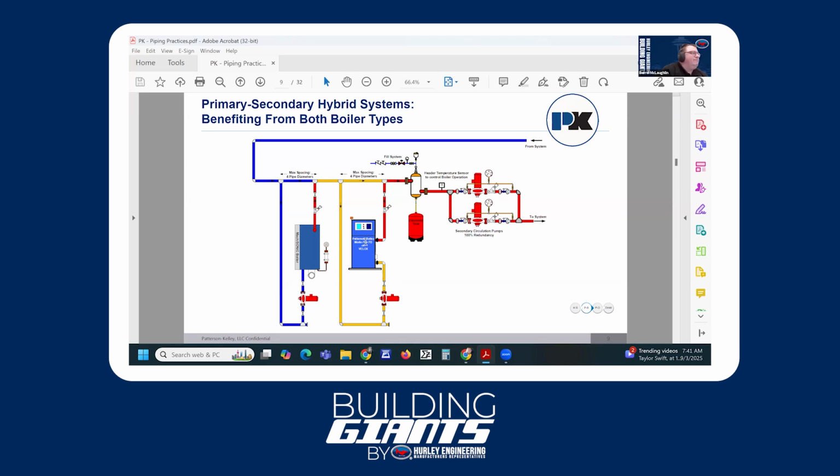Now that all relates to this: if we can get our return temps cool enough, then as they come back into the boiler, it cools our exhaust gases to the point where we drop below the dew point, and the moisture in there begins to condense. And once we get to that point, we'll capture all that latent energy that's still in our exhaust gas, and then we can get that energy and put it back into our system instead of out through our stack, right?